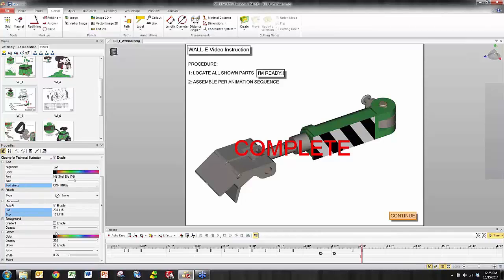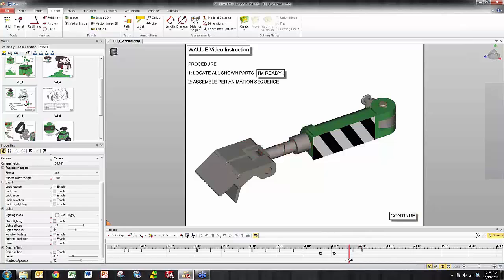And now because I've changed this as well as the location of this button, I need to highlight those properties and make sure that those keys are set within my animation. I'm also going to hit the set as neutral property so that when this first becomes visible, just after 41 seconds, it already says continue. So I'll set that as neutral. We'll come back here. Let's just ensure. I'll unselect it here. And our continue button.